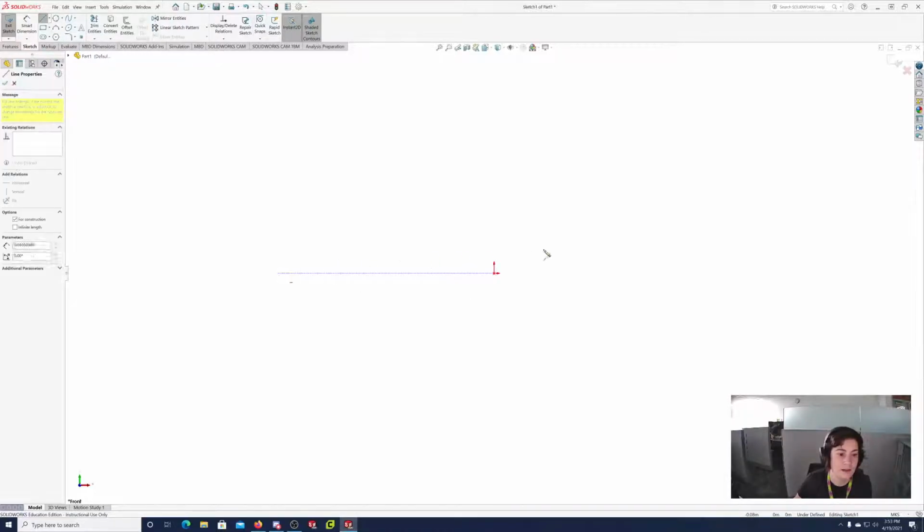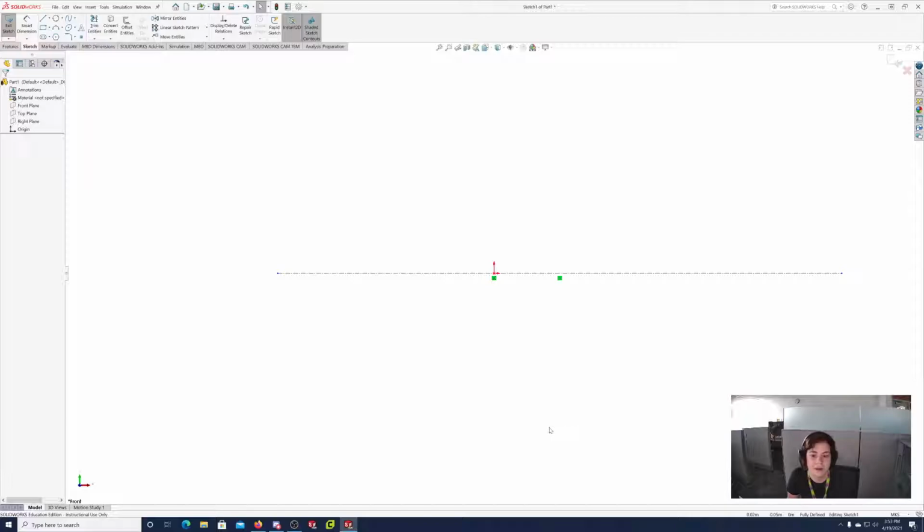If you add a center line to a fully defined drawing and you don't define the center line, it won't affect whether your drawing is fully defined. You can see I added this one, and I have nothing else in here right now. But even though there's no dimension on this center line, it still says fully defined in my lower right corner.